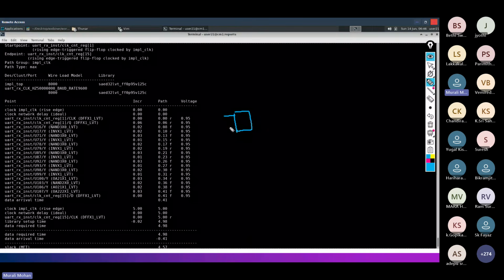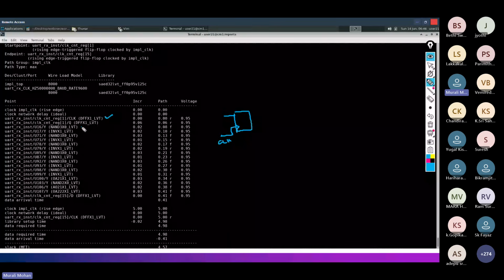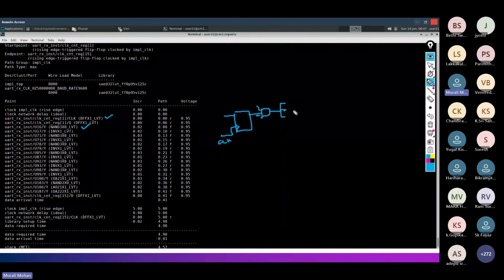Next, there is a NAND gate with a 3, meaning here one NAND gate is there. Somewhere some input is coming to this one. So it is capable of driving three things. Next is nothing but an inverter. For example, this is connected to one more inverter. So how much delay is being created by this particular NAND gate or register?